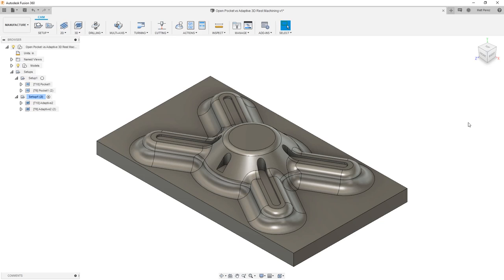And this is simply because the adaptive toolpaths and adaptive rest can take large cuts going down in the Z direction, and then it can take smaller step-up cuts getting closer to that final geometry. This adaptive nature in how it approaches step up and step down is a humongous benefit when it comes to removing material from complex geometry, but also keeping in mind that adaptive toolpaths in general will keep a consistent load on the tool rather than engaging a lot of material when you get into corners, such as the area between